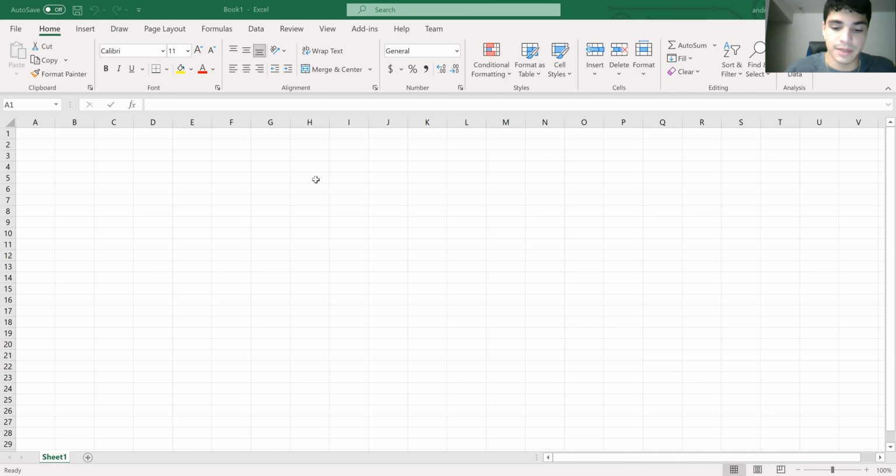And then we want to get the max CL over CD value, because this is going to tell us basically what point we want for the optimal angle of aerodynamic performance. So we're going to hit max, and then put it for the H column. It's going to be H13 through H33.